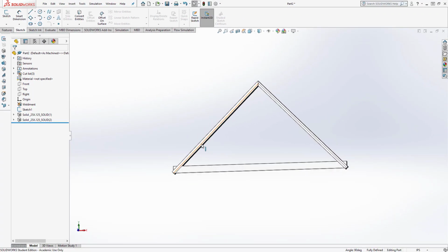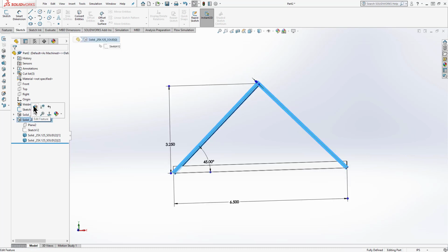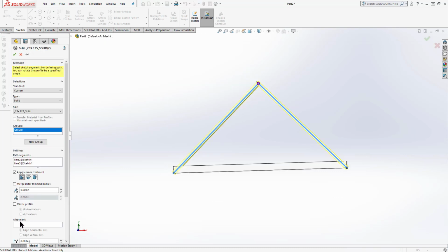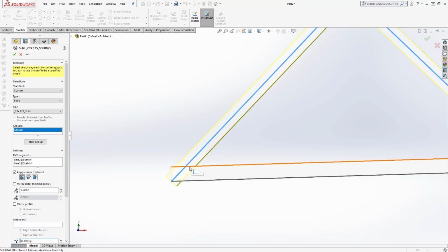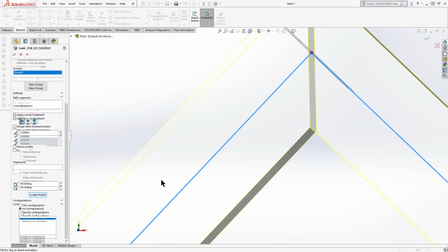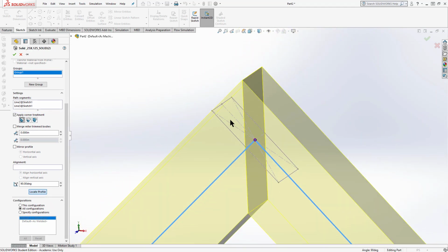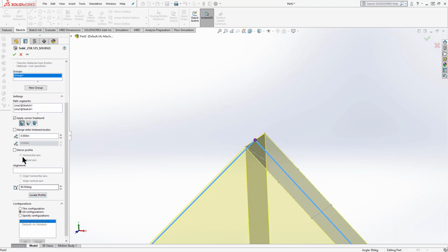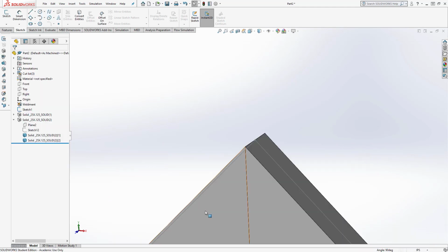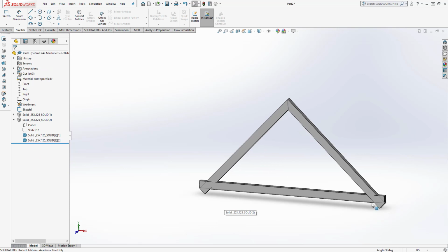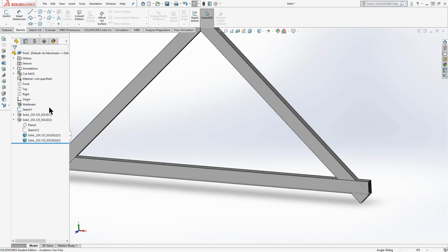Now you see I got an ugly truss, and I forgot to rotate it. So we'll go back and edit that, and I'm going to do my rotation, 90 degrees again, and select my locate on it. And you'll see again, I want this to be the top member in my truss. So remember, we want that size to be exact. And accept it. So now I got a truss, looks about right, but a little ugly there on the end. So let's go ahead and trim this up.